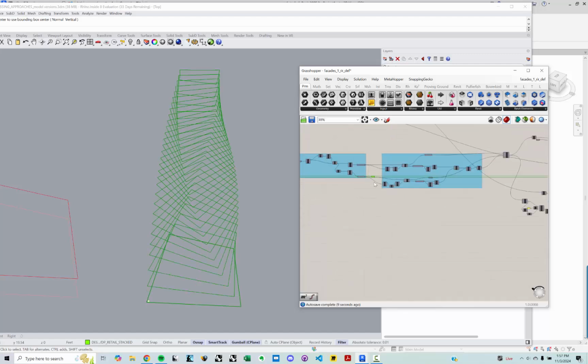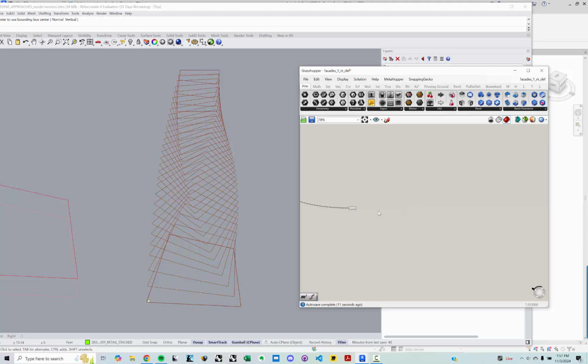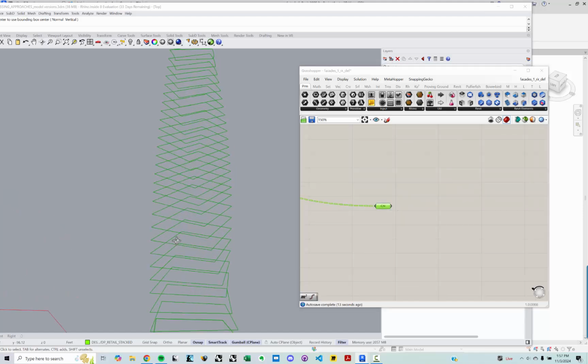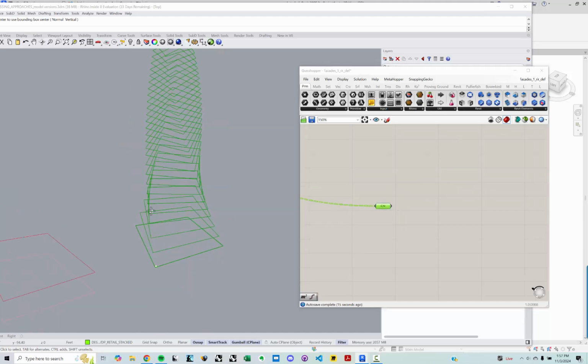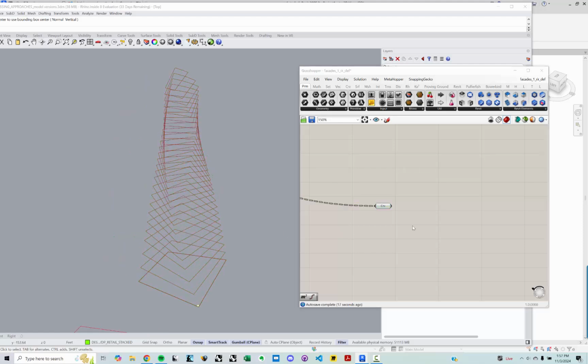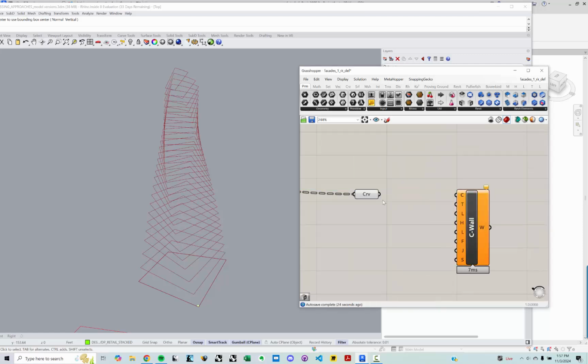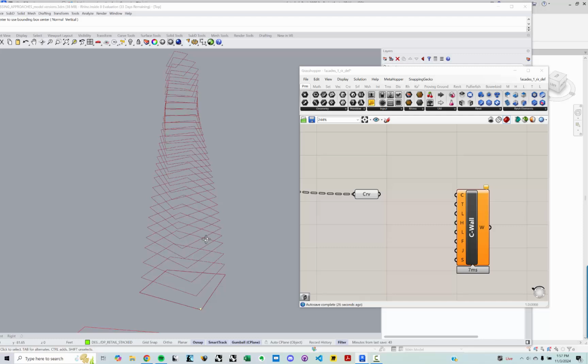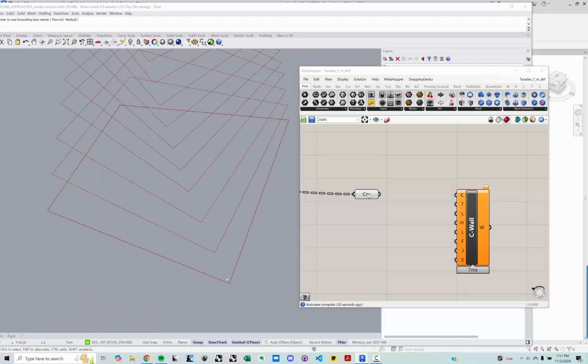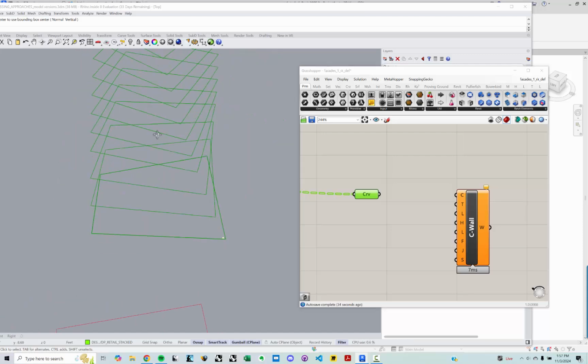So I'm going to take this, pull this down, and this is pretty easy. So right here what I'm going to do is wall, add wall by curve, and you have to explode this curve because right now it's a linked set of curves that's joined, right?